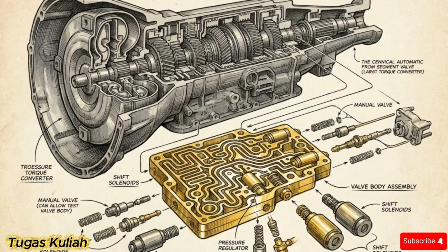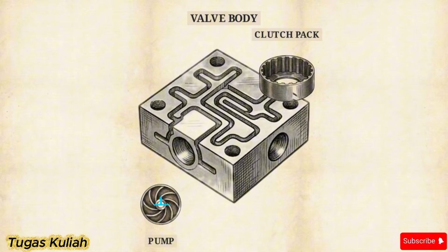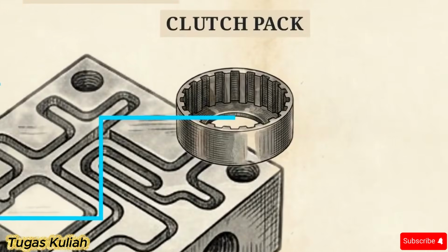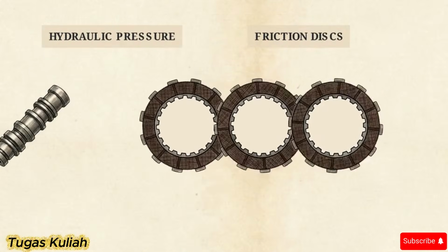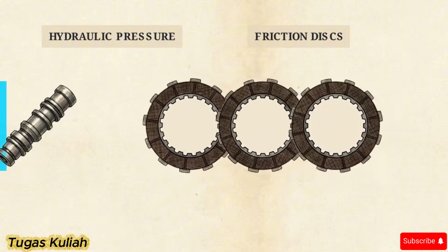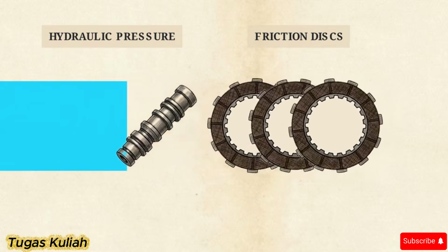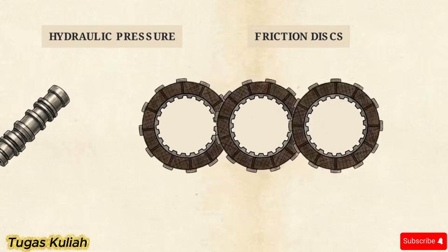Returning to the conventional automatic transmission, we bypass the heavy planetary gears and look directly at a component called the valve body. This schematic maps the valve body, the hydraulic brain of the transmission. It is an intricate maze of microchannels responsible for directing pressurized fluid from a central pump out to specific gear nodes. If we follow a specific pressure path, we can see how localized hydraulic fluid clamps a wet clutch pack together, securely transferring torque through the gears. Without exact, sustained hydraulic pressure, that clutch pack will not clamp fully. The internal gear plates will slip and spin against each other.